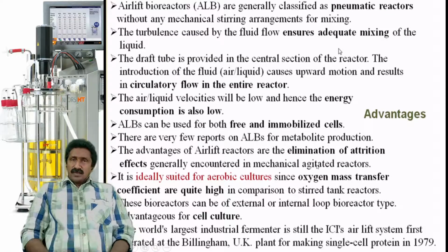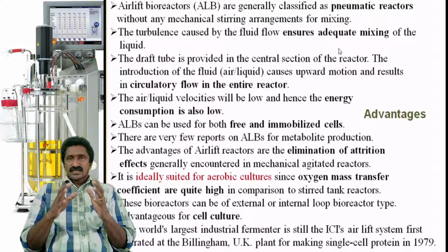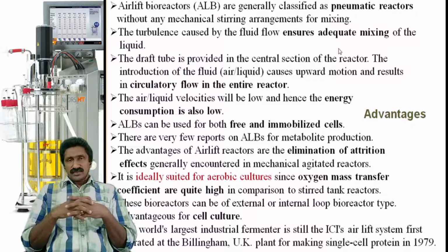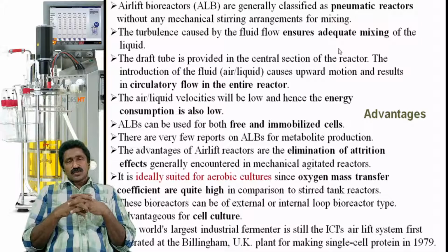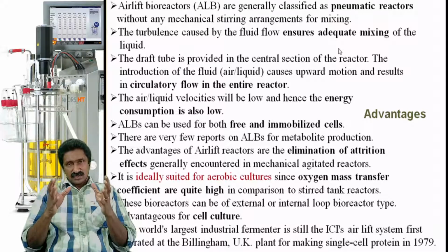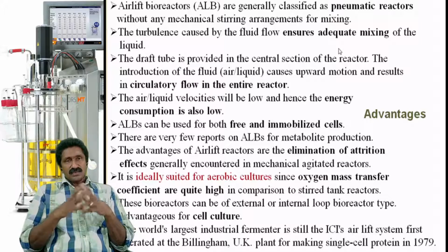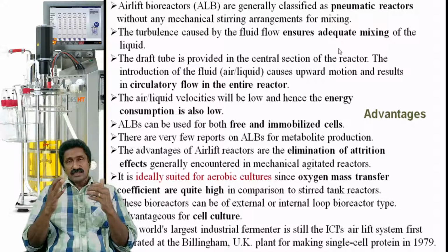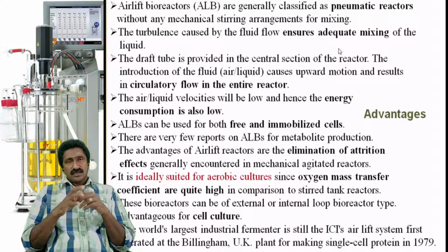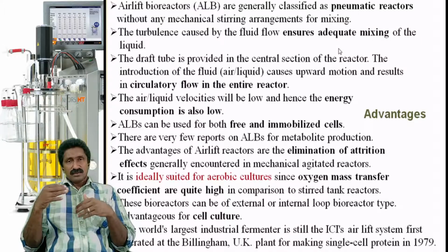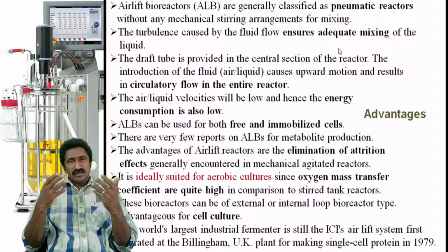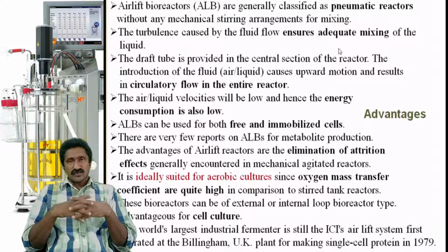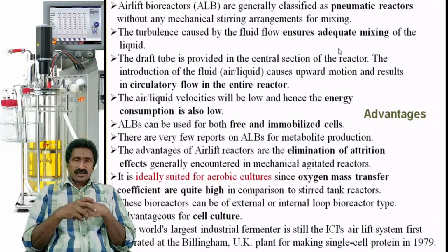Now, airlift bioreactors are generally classified as pneumatic reactors. And this slide shows the advantages of airlift reactors. They are known as pneumatic reactors, without any mechanical stirring arrangement for mixing. Usually in a CSTR there is an impeller which provides the mixing, but in an airlift reactor there is no such provision for mechanical mixing or stirring of the medium.